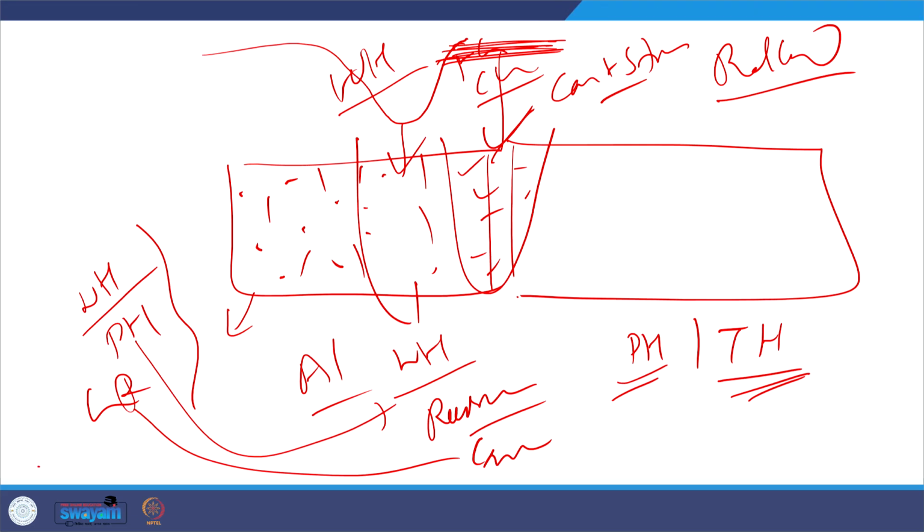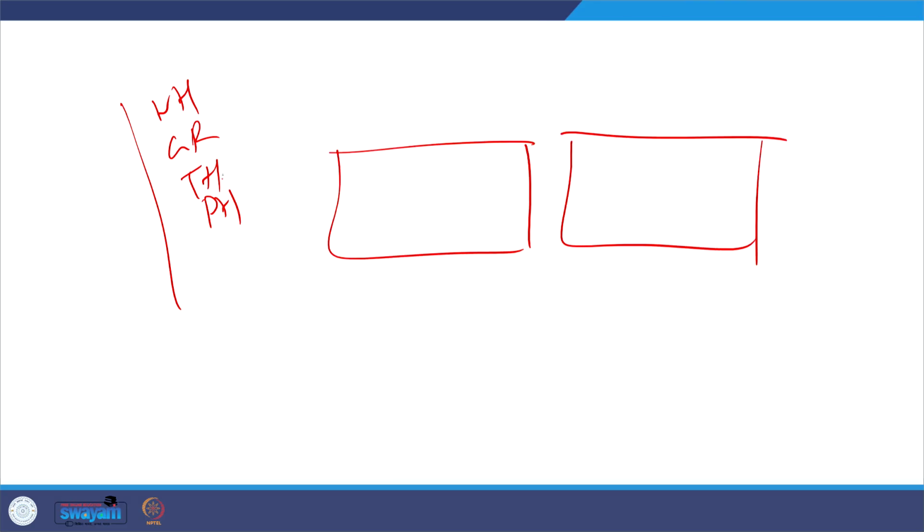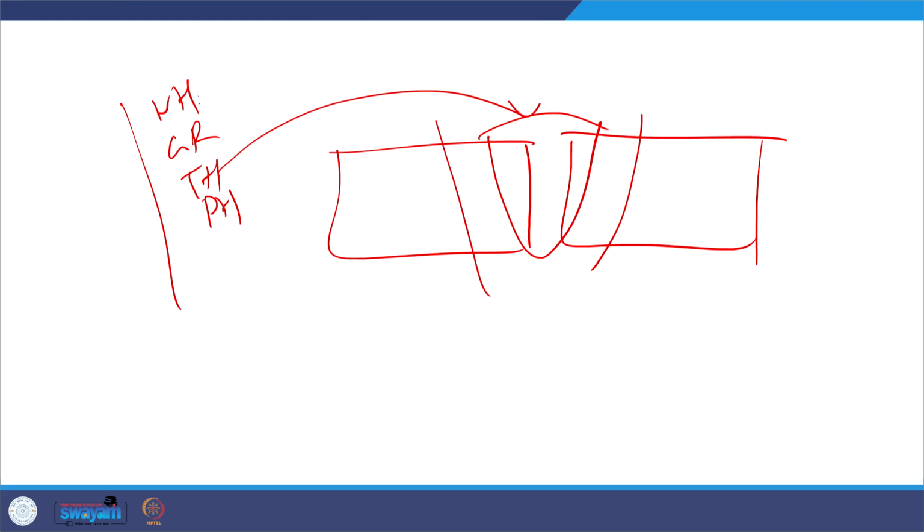The point that here I am trying to make is like if the metal is strengthened by work hardening, grain refinement, transformation hardening or precipitation hardening, a given metal can have the effect of the multiple mechanisms. It is possible like one mechanism may compromise, like in fusion welding of the steel, it is possible that we may be getting the transformation hardening effect in the weld and in the heat affected zone, but at the same time work hardening effect may be neutralized if it has been rolled out. But which effect is dominating, that will ultimately govern and determine the properties of the weld joint and of a particular location.